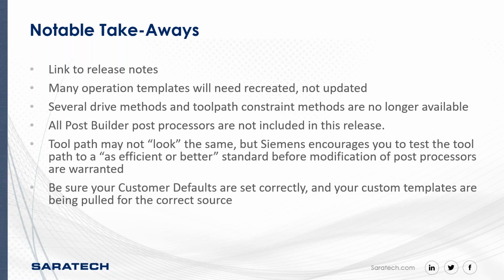If you run into an issue, go to your previous release, NX12, resource folder, post processor folder, copy the whole thing, paste it into this release, and just don't overwrite what's already in there. If you have your own post processors that are currently in there, just don't overwrite those and only add what's missing.